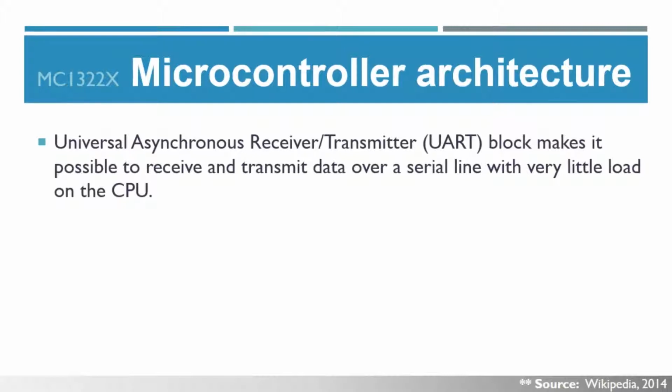This is useful for devices such as thermostats, which periodically test the temperature around them to see if they need to turn the air conditioner on or the heater on. A dedicated pulse width modulation block, known as the PWM, is also another important section of the chip, but it will not be talked about in detail in this presentation. It's generally a block that makes it possible for the CPU to control power converters, resistive loads, motors, etc. without using lots of CPU resources in tight timer loops.